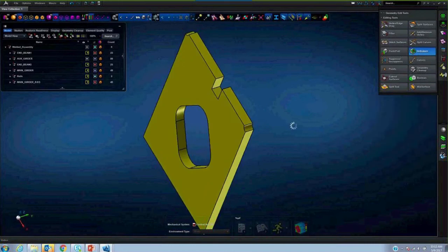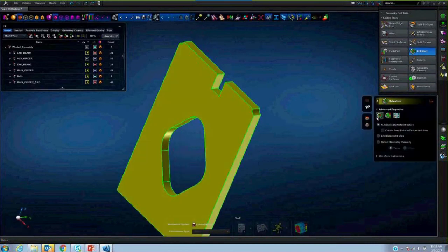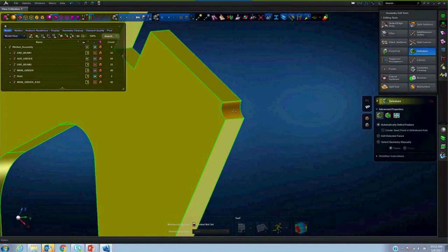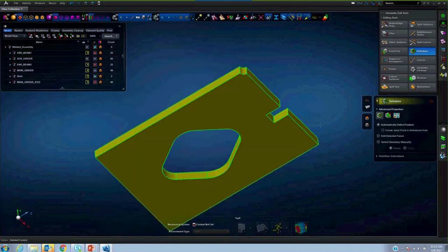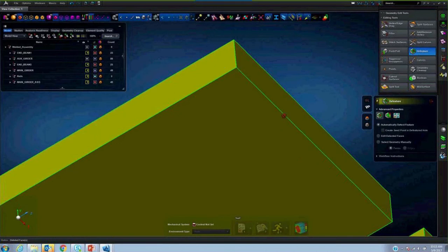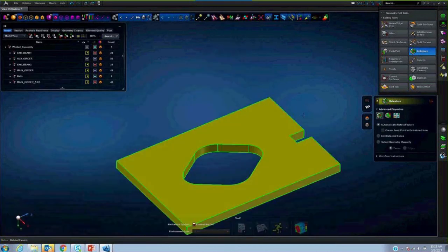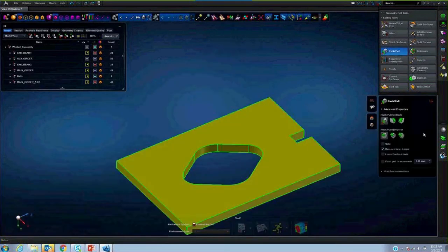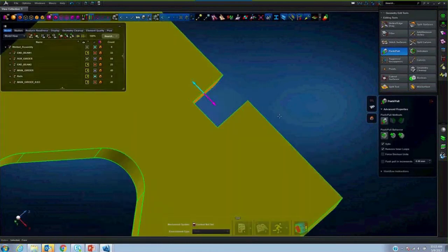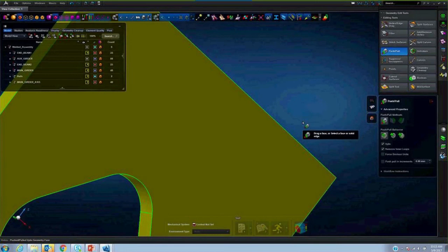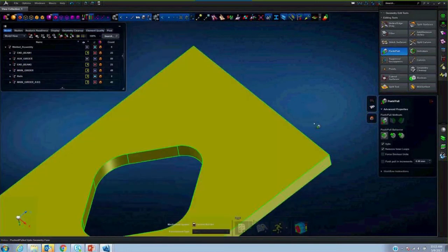And under the defeature tool, now if I would like to delete some of these fillets that are unwanted in the geometry for the simulation purpose, can I delete them? I defeature them. It is as simple as that. Can I remove this notch using this push-pull tool? I can simply take that one and extend that to that and delete that notch.